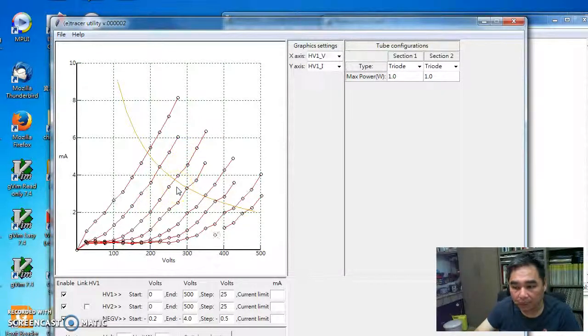And this is only 256 times average. If we modify the software, I can provide even more averaging. I'm thinking of doing a 1024-sample average, for example, and that will provide a much smoother measurement result.